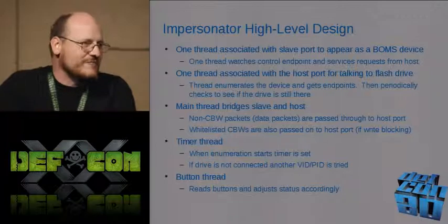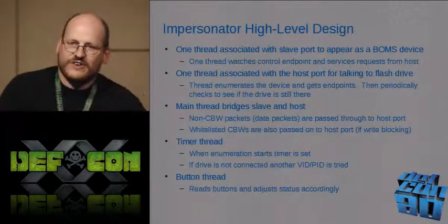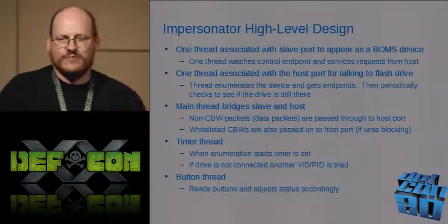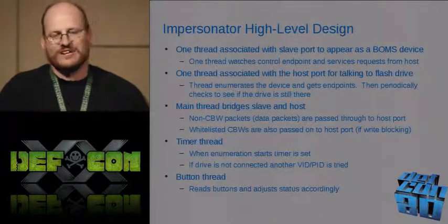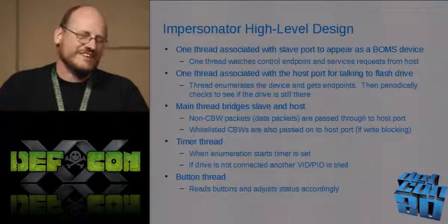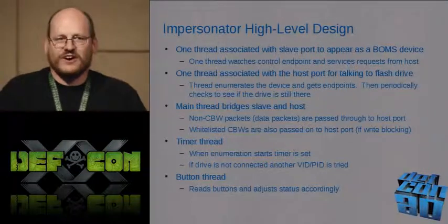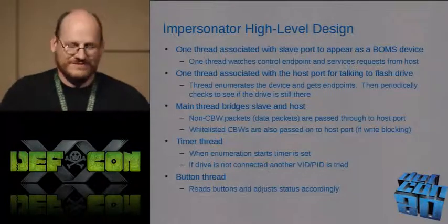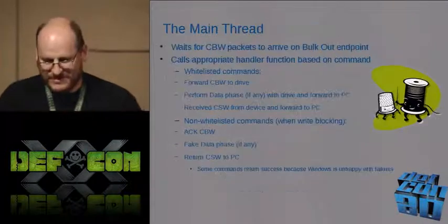Also, there's a timer thread, and what the timer thread does is, if you're in the automatic mode, whenever the PC asks for a device descriptor, it says, oh, someone's trying to talk to me, and it starts a timer. If they stop talking to you after a second, and they don't ask for additional descriptors, it says, oh, someone's blocking me. I'll go to the next one. And that's how that works. And there's also a thread for reading the buttons that come in.